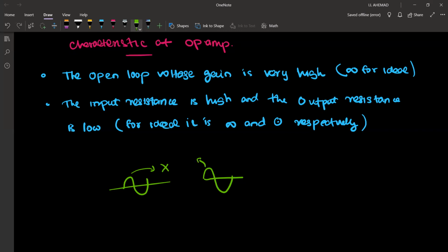Finally, when we were comparing BJT and JFET, we discussed why having high input resistance is better, because it won't distort the signal. It is not going to absorb any current from the signal. At the same time, when the output resistance is low, everything will completely leave. There won't be any leftover. Is that idea clear?